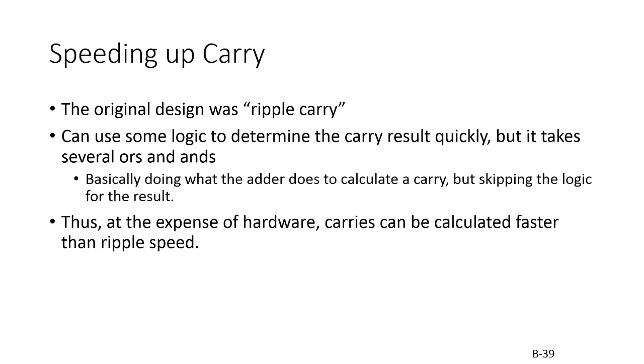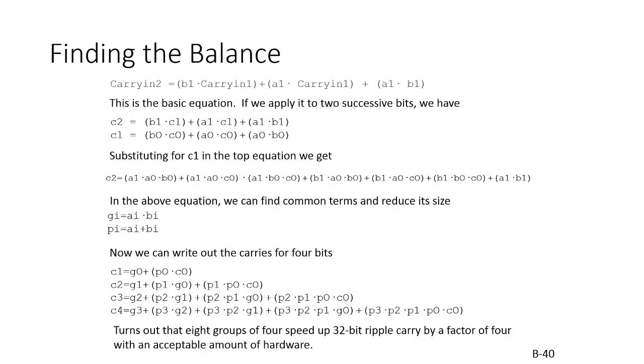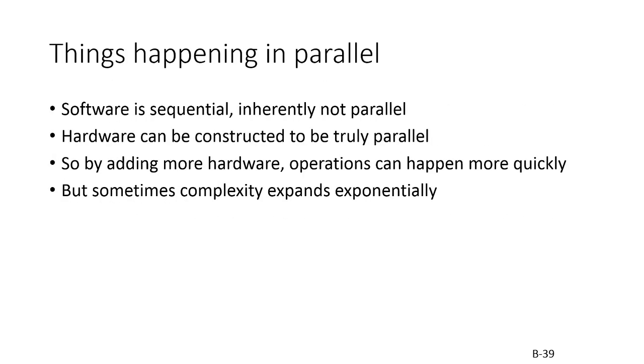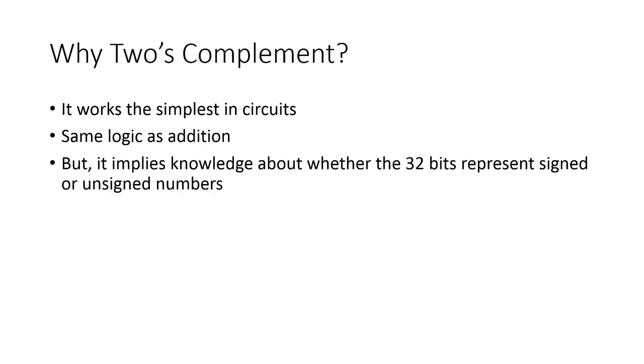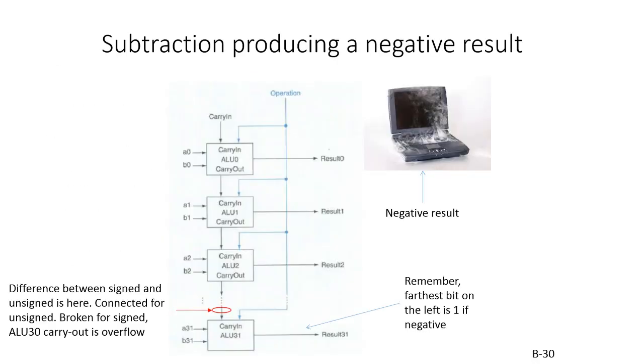Okay, now let's transition and talk about arithmetic with a standard carry. So we talked about setting up a carry which is called a ripple addition with a single bit adder, and each single bit adder just flows the carry into the next.